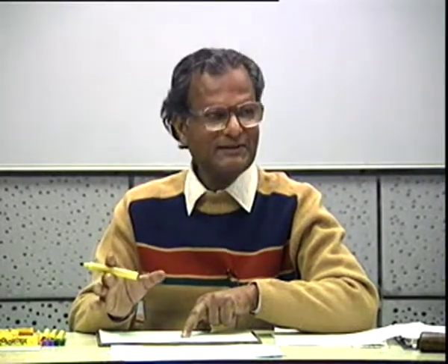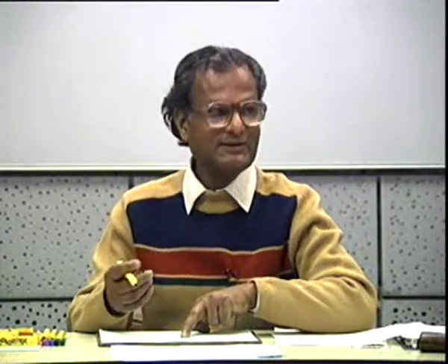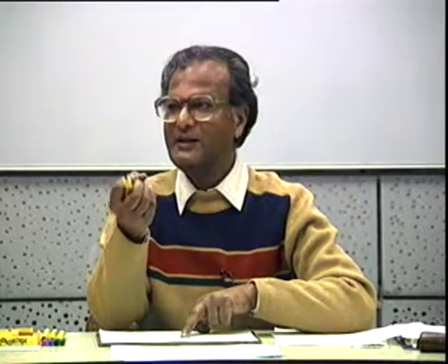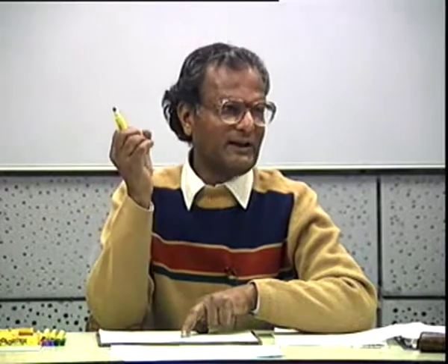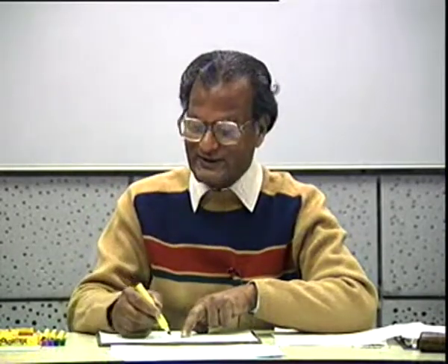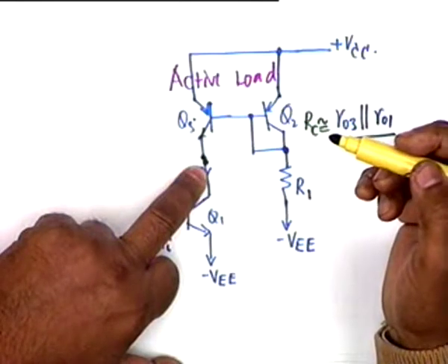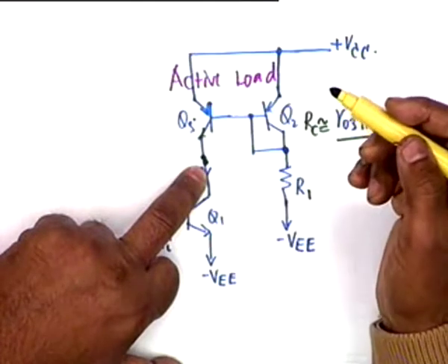The collector area is much larger than the emitter area. In a fabrication of a transistor, since the collector causes the main dissipation, the silicon area for the collector is much larger than the emitter. Therefore this is the natural mode, and we shall have a problem if emitter and collector are interchanged.